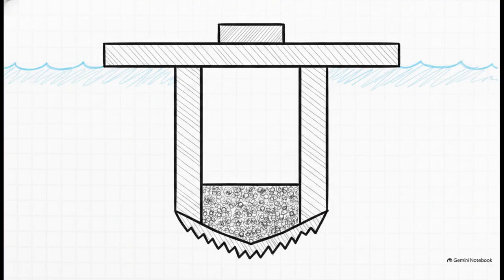Finally, let's get into Section 5, Anatomy and Construction. So how exactly are these underground wells put together? Let's quickly break down the anatomy so you can grasp the specific vocabulary engineers use. The main body or the wall of the well is called the steining. At the very bottom is the cutting edge, which is heavily reinforced to actually slice right into the soil. Just above that cutting edge is the curb.